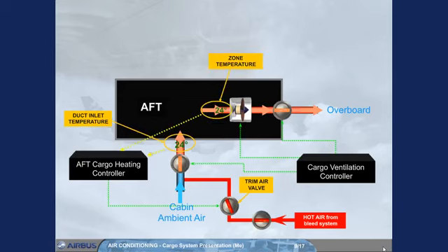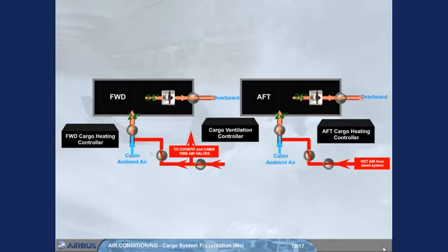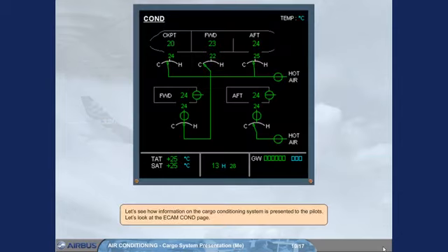Note: compartment heating is not available when the aft cargo door is open or when the cargo pressure regulating valve is closed. Let's see how information on the cargo conditioning system is presented to the pilots. Let's look at the ECAM CON page.